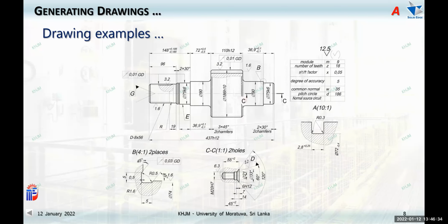All these details are very important in order to complete your drawing. So if you have a straight shaft, then there's nothing. I know one might find it difficult to machine that one because the bearing surfaces need a bit more fine finish. And then there should be some locations to position the gear.